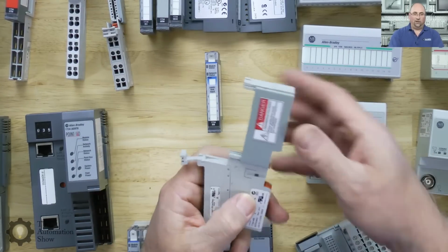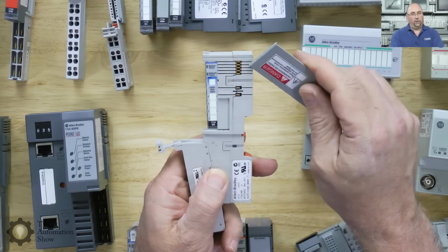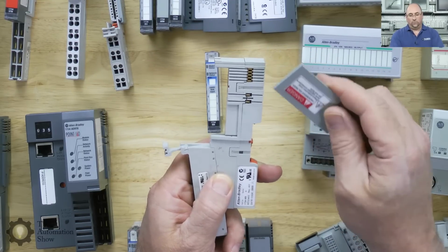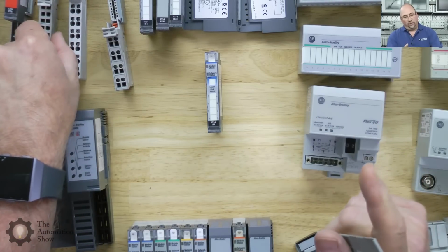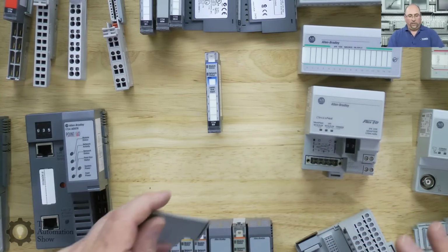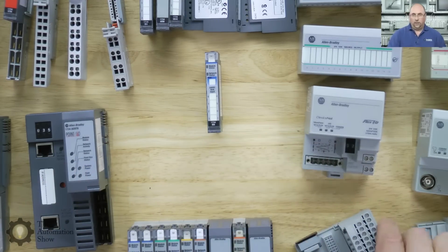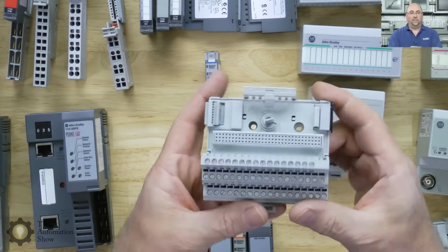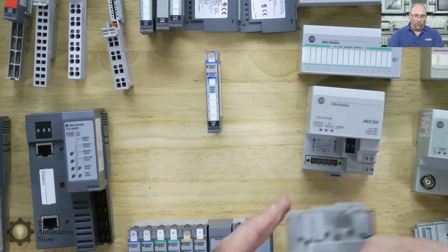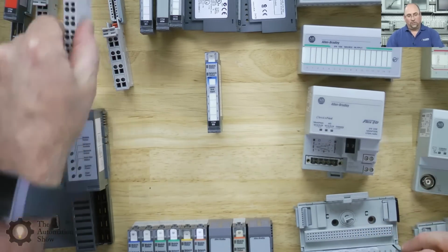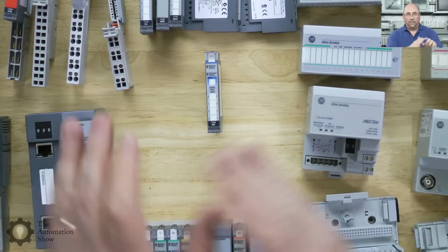Whoops, going to take the cover off here. Okay, so we have power for the electronics and the modules, but we also have the field power bus. So that's another thing. If you needed to start with DC and then go to AC, with Flex-IO it's not a problem because every base is isolated. Well, with Point I/O, because they have this common power bus going through all the terminal blocks, you would need to isolate that.